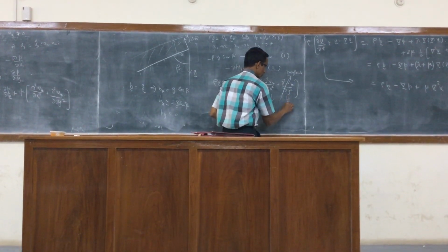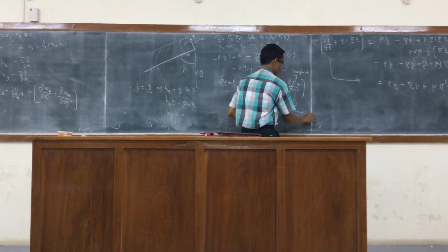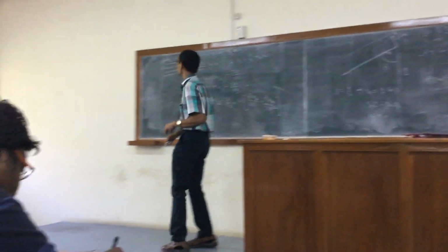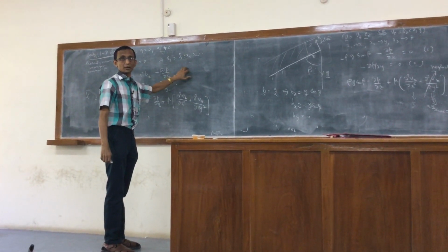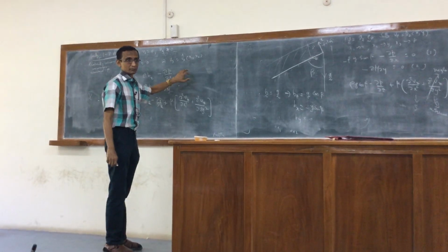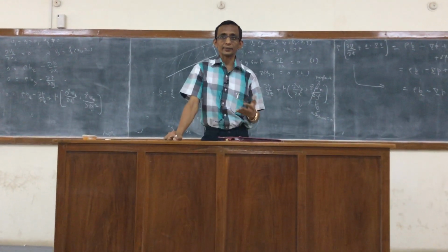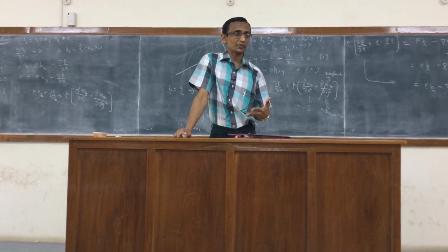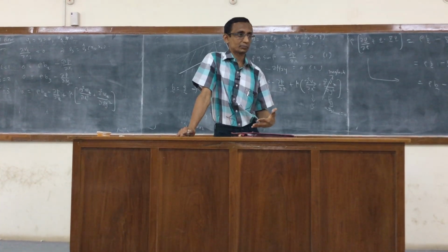So we assume that this is equal to 0. This has to be distinguished from the non-dependence of Vz on z, which follows directly from the continuity equation. That is not an assumption. The moment you say that I am neglecting all the components other than Vz, for the continuity equation to be satisfied, we cannot have any variation of Vz in the z direction.